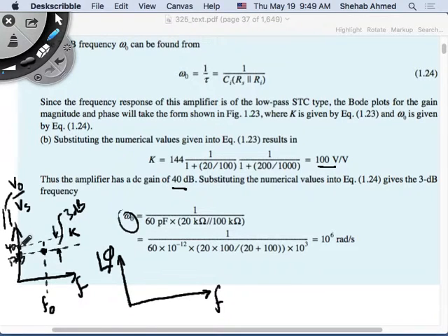So then I can plot. I can start at 40 dB, and I don't know how exactly it will look, but I know that at the 3 dB frequency, at my corner frequency F naught, it will go down 3 dB. How does it move from here to here? I'm approximating here. You have to plug in values. F is equal to, instead of 10 to the 6th, take 10 to the 5th, 10 to the 4th, and so on. Take every single point and plot it, if you want to plot it in detail. But I don't care. I'm just plotting numerically, just an estimate.